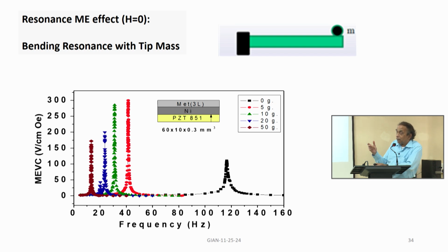So you have the mechanism here. You have the liberty to tune the resonance to the frequency that you really want. You can manipulate the resonance, and based on what kind of magnetic field you are going to measure, you can tune the resonance. Then how do you measure the unknown AC magnetic field? It's rather easy. So you are going to use two different AC fields. One at resonance frequency, the second one that you want to measure.